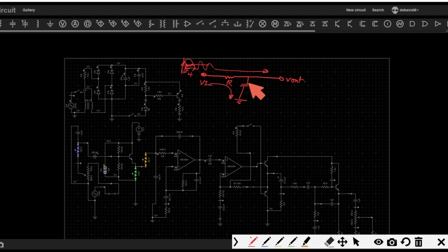Now this is happening because of the property that the reactance of a capacitor reduces when the frequency increases. So using that concept, this kind of circuit can be done. Now based on that, you can get a cutoff frequency which is 1 by 2 pi RC, this formula. So this will show you till what frequency it is going to allow, and beyond what frequency it is not going to allow.